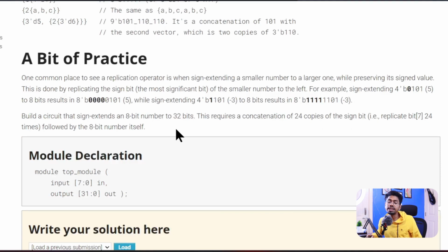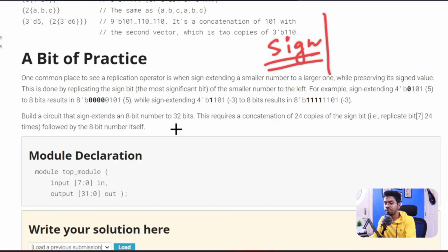They are saying there are many other applications, but one of the major applications is anytime you want to extend your sign bit. Now many of my junior students, first or second year, and probably senior students, will ask what is meant by sign bit. In binary we need to have signs, right? Plus, minus. I am not explaining everything here; if you are confused, for sure go to number systems again. But roughly, to recall: the leftmost bit, if it is a sign bit, will give you the sign. If it is 1, then your number is negative. If it is 0, then your number is positive.